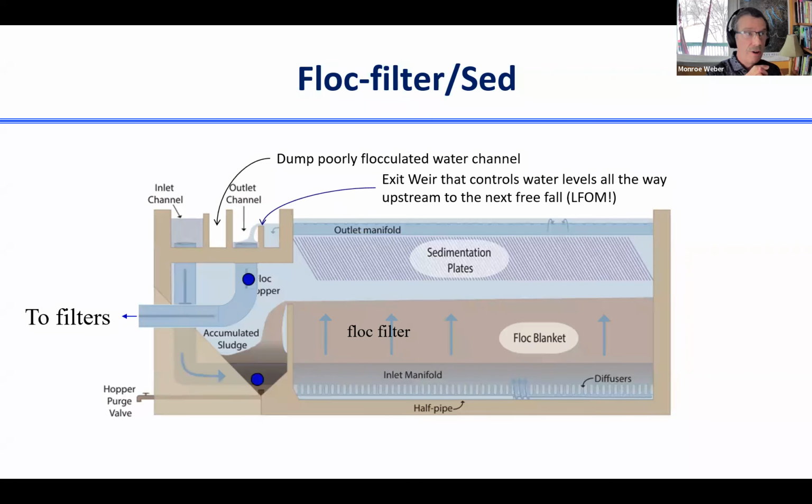I will show you another view of that. The water is forced down because there are little pipes that it is forced to go in that take it to the very bottom of the sedimentation tank. And then there's a little, what we call a jet reverser, that turns it around and sends it back up. So I'll show you another view of that.